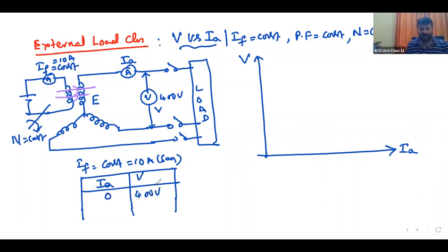Where will the curve start? Because we have given field current and are rotating, it cuts the flux and EMF is generated. Under no load condition, V is equal to E, with current 0. Let me take this as a reference. This is not the characteristics, just a reference.